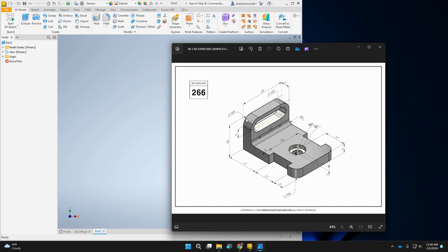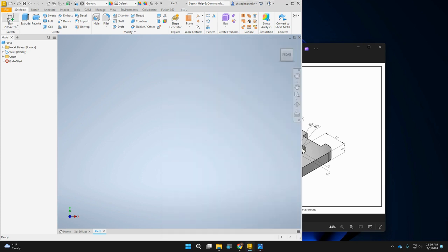And so two options, probably both about the same. I can make an L that goes like this and then all the way across to the front. Or I can make a rectangle on the bottom and then extrude this part up. Doesn't really matter. I'm going to flip a coin and let's do the bottom. Okay, so we'll create a sketch on the bottom surface.